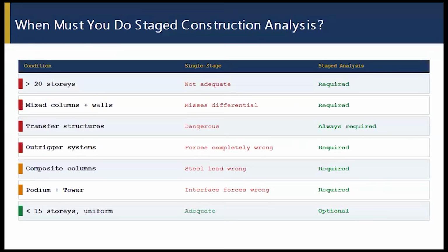Okay, summary and practice. So single stage is not adequate, you require multi-stage. We miss the differential settlement. It's dangerous for transfer structures, outriggers. So this is just a summary of whatever I just mentioned, we summarized that for when we have to do that.